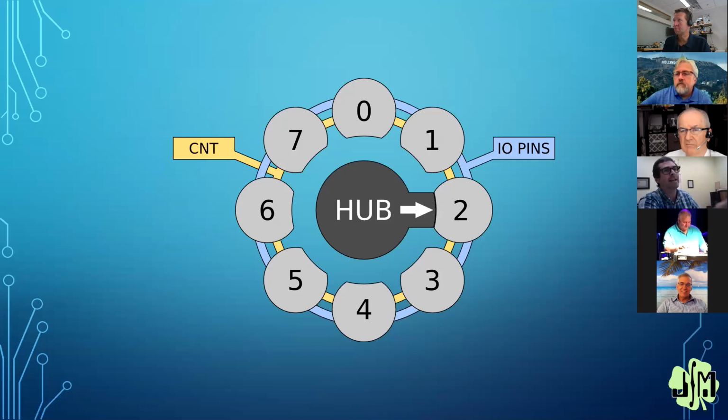The way it works is, let's say in this case we have 8 cogs, right? So there are physically separate memories for every long address that ends in the 3-bit pattern of 0, 1, 2, 3, 4, 5, 6, 7. So what happens is, as that thing rotates and all 8 connectors are switching around, every cog has access to the next memory location each time, but they're each offset by one long.